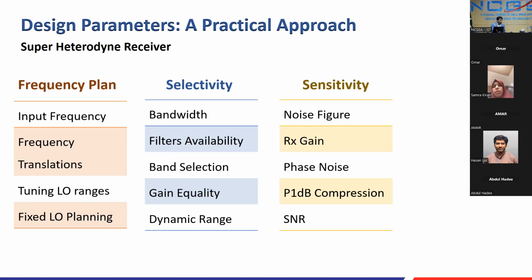I'm talking about positive SNR, but there are negative SNRs as well. People do fetch signals from the GNSS people. They do have signals embedded inside, so they have processing gains, I think, and then coding gains. They can fetch the signals below the SNR levels. So it all depends on which application you are targeting. You need to focus on that, which application you are designing the receiver for.